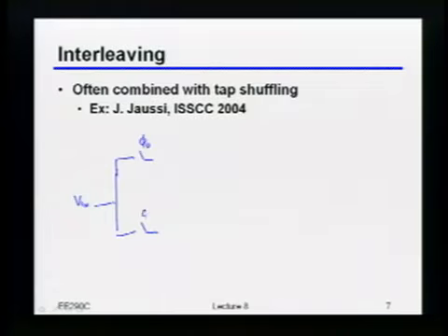So let's say here that that's phi 0 and phi 1, and by phi 0 and phi 1, this will basically be just clock and clock bar here. Okay, but each one of these will be running at half of the data rate. Okay? So now what I'm going to do is, as I mentioned, instead of just building one filter, I'm actually going to build two filters, each running at essentially half of the throughput. Okay, so let's say that this was my A0 and A1. Okay?